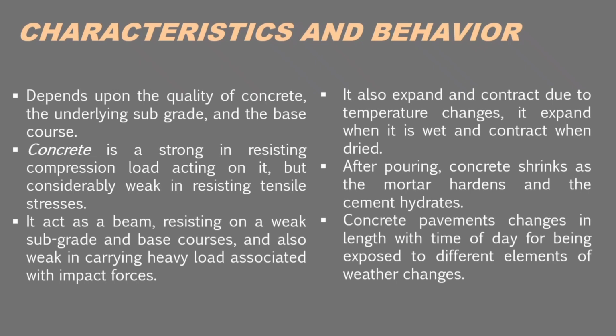It depends upon the quality of concrete, the underlying subgrade, and the base course. Concrete is strong in resisting compression load acting on it, but considerably weak in resisting tensile stresses. It acts as a beam resting on a weak subgrade and base courses, and is also weak in carrying heavy load associated with impact forces, and it also expands and contracts due to temperature changes.